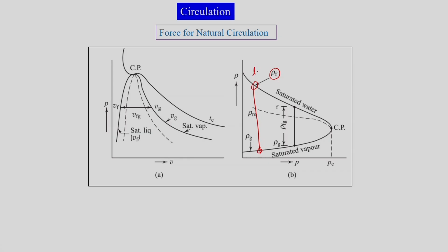So, we have liquid here and vapor here, and equally in the P-v diagram we can see that the large density corresponds to small specific volume, which is liquid here, and then we have large specific volume, meaning small density. So, we have vapor here and liquid here. So, this difference is huge.